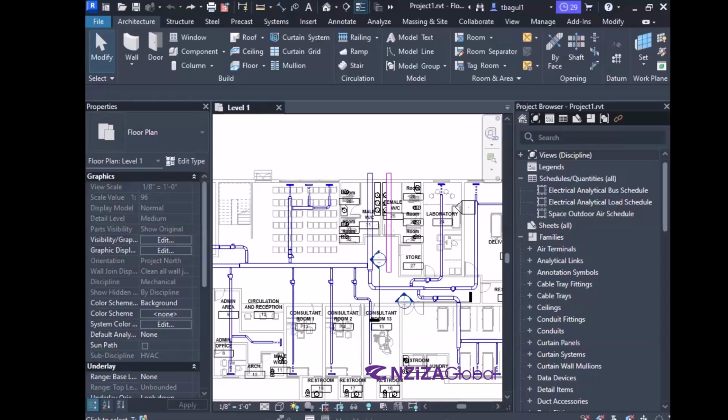All good, right? Okay, coming back to the point, we have a supply stream and then we will have a return stream. In the restrooms, we will have the exhaust stream, exhaust ducts, right? And on the air handler side, we will have the outdoor air ducts, the 4 ducts that we spoke about, right? So now we'll do the exercise of placing even the return air grill and checking how that works, going back to this point.